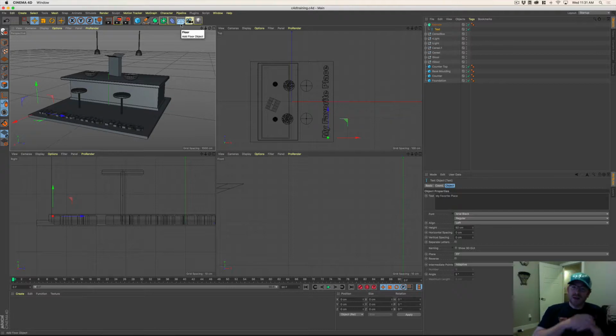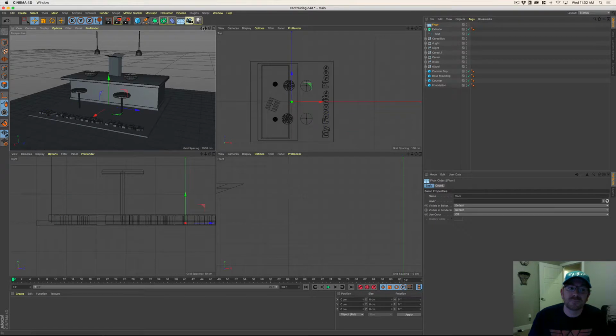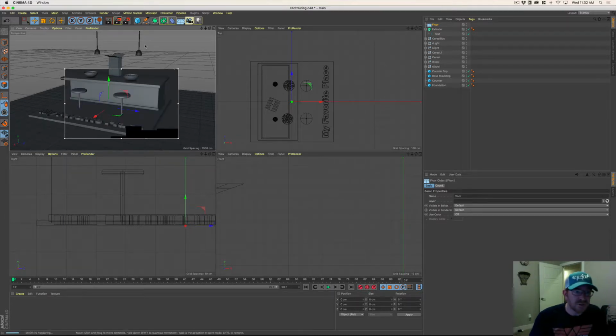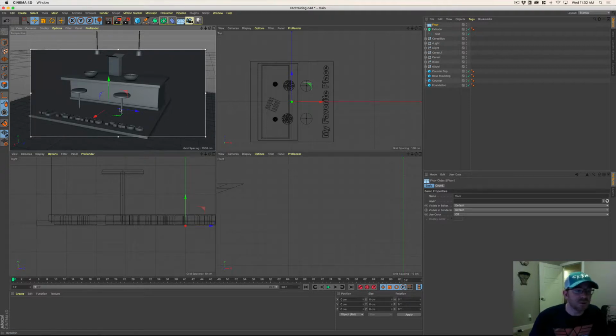We need an actual plane that's the floor, that's an infinite space. This guy right here, there's floors and skies and stuff like that, backgrounds, but we're gonna just create a floor. And this object looks like it ends, but it actually doesn't. I'm gonna pull it down so it's just below the foundation, kind of like that. Now if I hit my interactive render region, the floor never ends. It's just a constant plane. So it's a really easy way to create a plane.